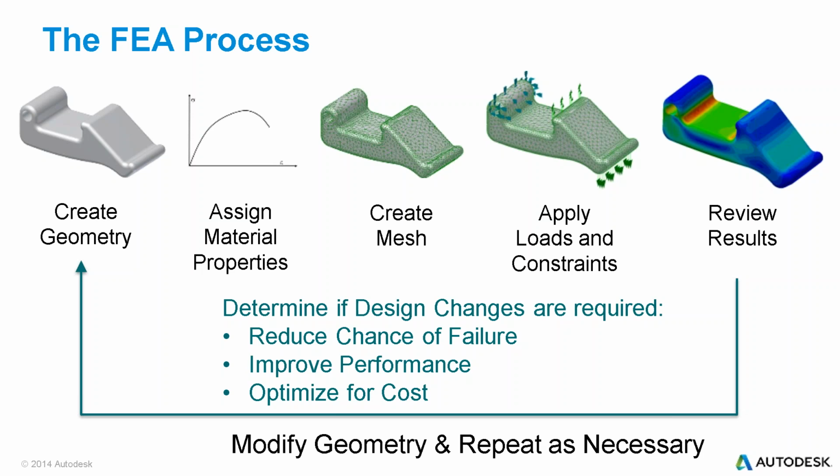Once you've got your mesh, you can apply your loading and constraint conditions, maybe do some mesh refinement in there, then run your analysis and look at the results. With all of this, the goal is to validate what you expect or what you are witnessing happen in the field. And any changes that need to take place, it's much cheaper and faster to make those changes and test that theory here in the CAD product than it is to make a prototype out in the shop or out in the field and test it under those conditions. It starts to get very expensive once you walk out that door into the outside world.